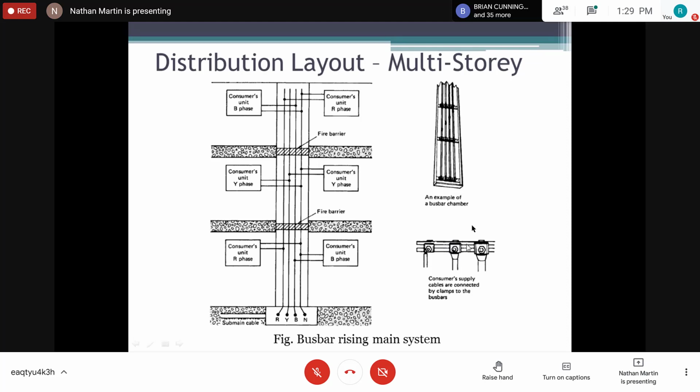And we will tell you about the lugs. And so these lugs, depending on the size of the current, may be crimped lugs or soldered lugs, right? So when we're talking about this, we have different types of crimping tool. For high current capacity conductors, we're going to use a hydraulic crimping tool, which is totally different than the one where you're using your hand and crimp a 2.5 wire, right? The hydraulic crimping tool is for crimping bigger wires of bigger cross-sectional areas, right? So we're talking probably a 50 mm wire. You're going to use a hydraulic crimping tool and so forth.